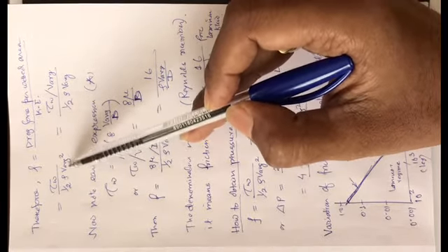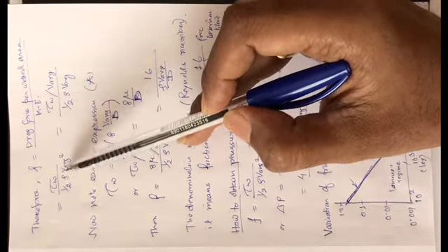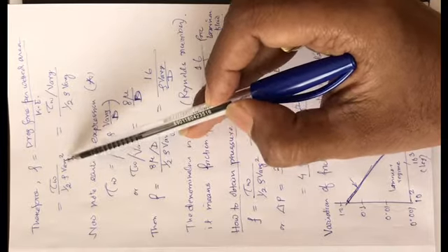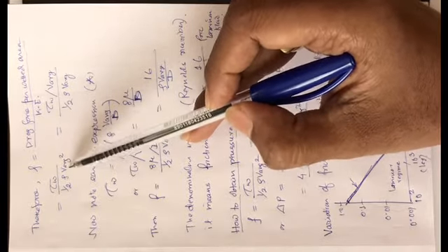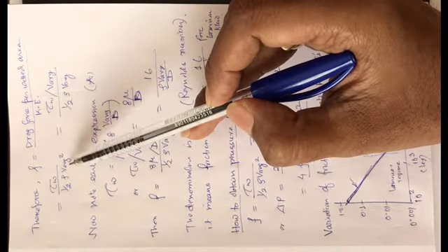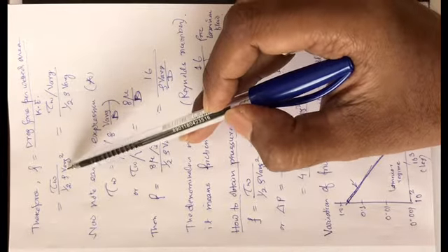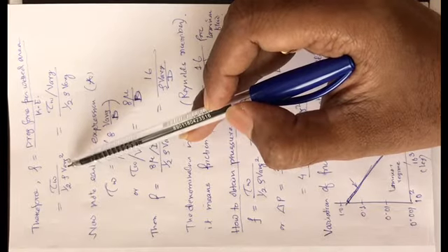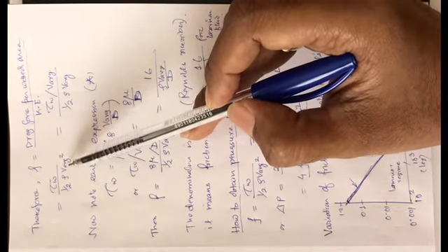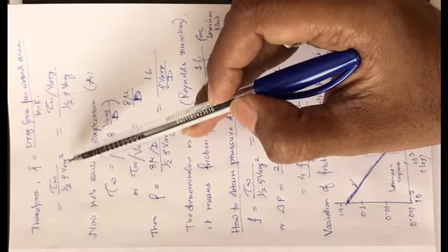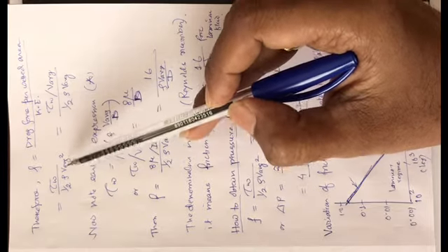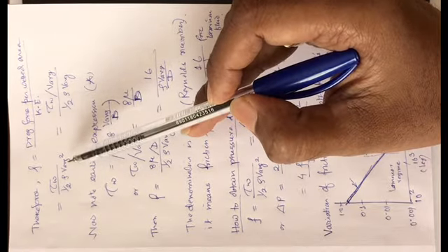Here you should always note that it is V average. This is the value of velocity you should take while describing the kinetic energy term. It is the average velocity, and experimental determination of average velocity is very easy. Just collect how much fluid is coming out from a tube in a given time, and divide the volume by the cross-sectional area of the tube and by the time. Then you can get this V average.